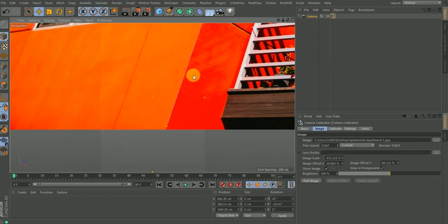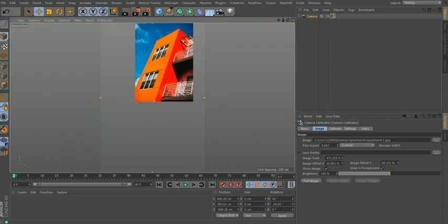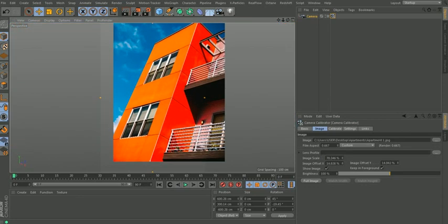Alright, so for me to identify or to specify what axis I want to turn this line to, I have to hold down my shift key on my keyboard, then shift click. So the first time I click, I'm going to have the red axis. You can see that. The next time I click, I'm going to have the green axis, and the next I have the blue axis. But don't forget, this is meant to be my y axis, so I'll click several times until I have the y axis.